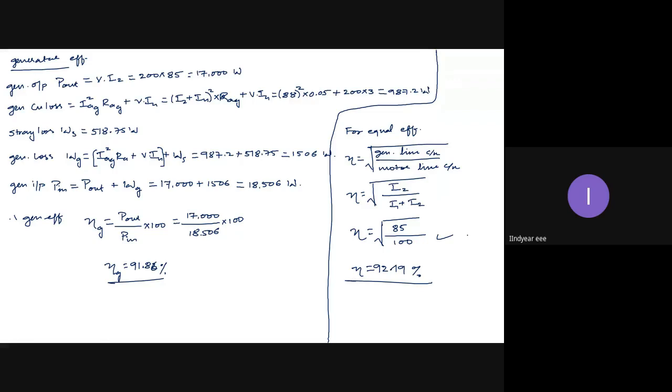If I don't know the losses, then estimation of temperature rise at various losses will not be possible. Therefore, the efficiency equation with equal efficiency consideration is okay to find the efficiency, but it will not give the entire performance information of the machine. Complete performance evaluation is not obtained using that.